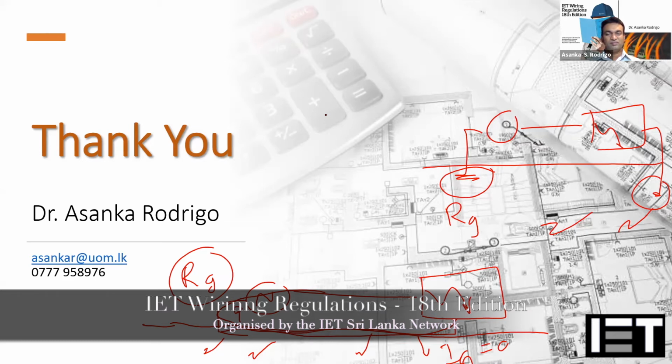Is it needed to install a 100 milliamp RCD at the meter panel if the service cable of a domestic supply, 30 ampere, is laid underground from the meter panel to the MDB? Question is clear? Yes. Normally, we are not installing the RCD there because we are assuming that the meter point is the starting point of your installation.